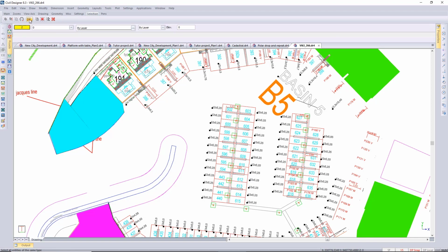So I've just left clicked on the select same, so it's applied that to all that text again. Remember, if you right click on your icons with that little black triangle arrowhead in the corner of the icon, you get the flyout. So then you can see all the different options that we have under the select same icon.